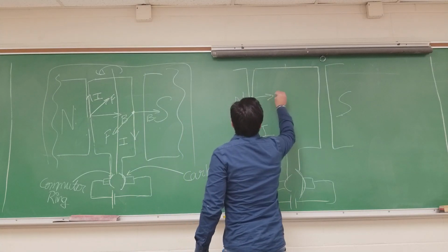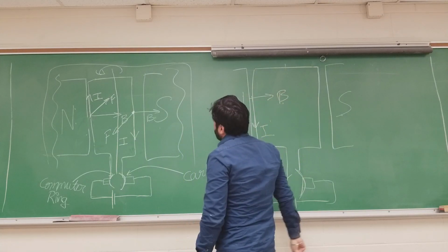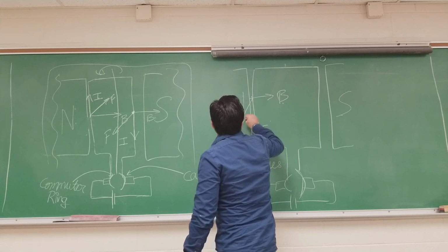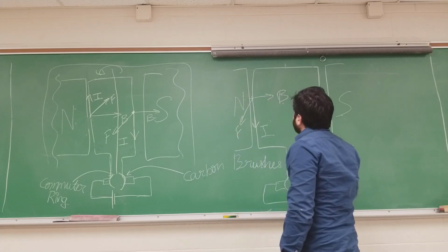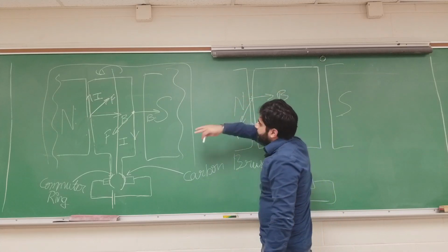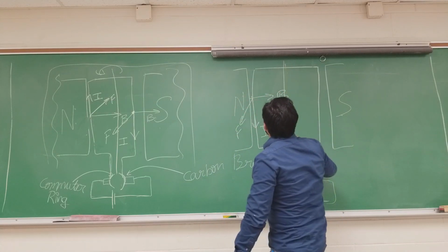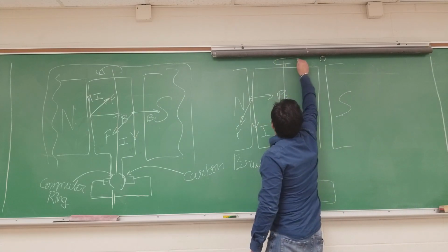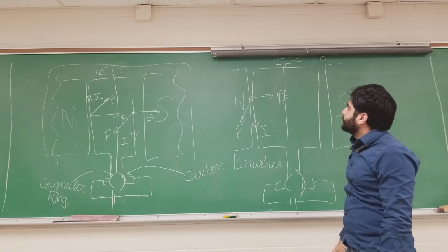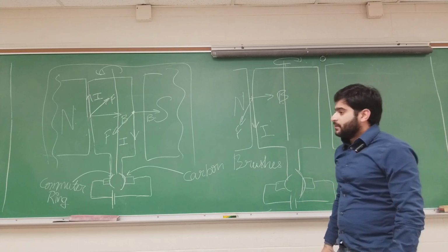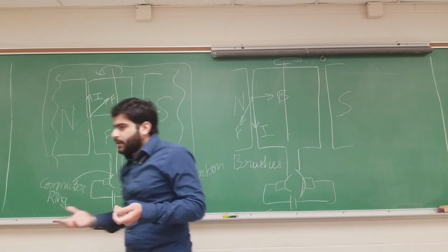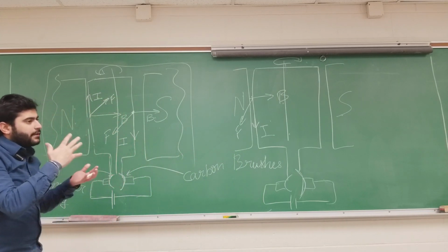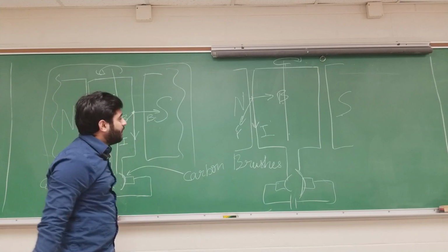However, B is the same, and the resulting F will be coming out of the plane of the paper. By similarity, we will have a rotation in the opposite direction. So our motor will try to rotate one turn clockwise, one turn anti-clockwise, one turn clockwise, one turn anti-clockwise.